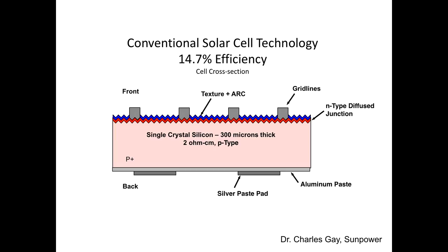So this is a classic silicon type architecture where you have P-type silicon. Silicon uses a homojunction. The silicon is about 200 to 400 microns thick, which is still really thin, but when I talk about thin film solar cells, you'll see why they're called thin films.